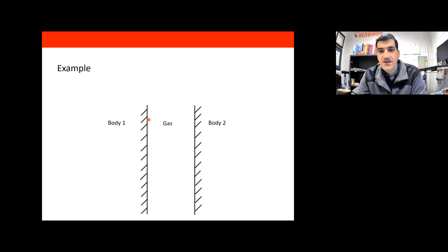If your gap here is too large, then like we just said, you're going to get a natural convection circulation here, which is going to increase the rate of heat transfer, because convection, like I talked about earlier, is a faster form of heat transfer than conduction is. So if there's too much separation between the window panes, then you're going to get natural convection in the gap between the window panes. But if that gap is too small, then you're not going to get natural convection.